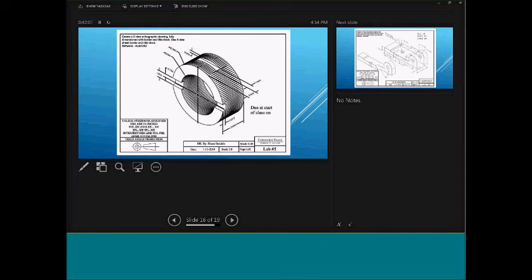This is one of my favorite labs because they always get the hidden lines wrong for this. If you look at the front of that cylindrical body, there's a groove that runs through the front of it that's kind of machined out. And that creates some really weird setbacks in what that groove looks like in what I would call the top view. Universally they get this wrong because they're not transferring the changes in direction of surfaces correctly.